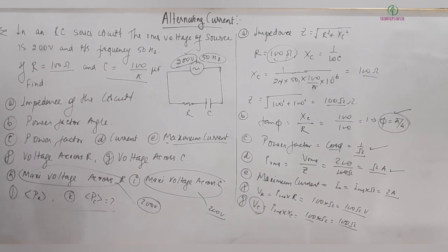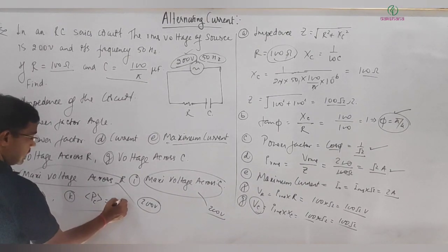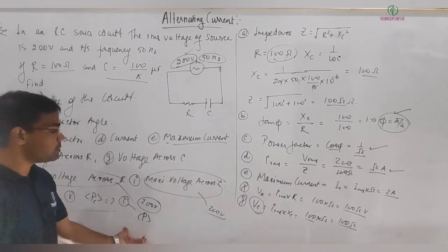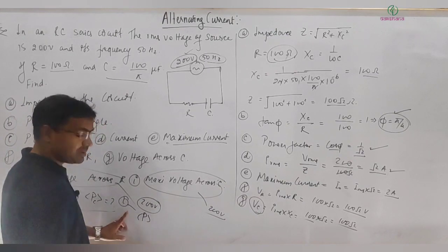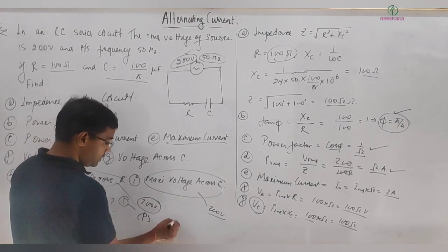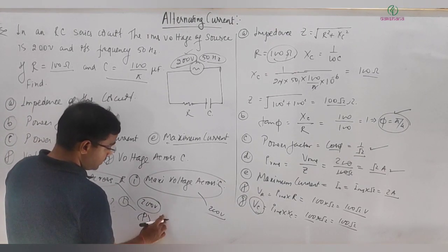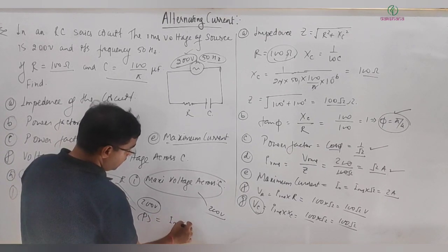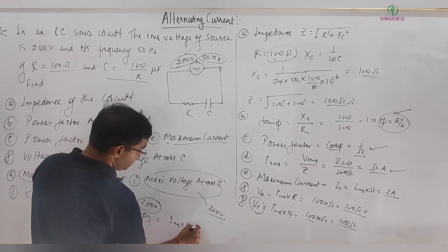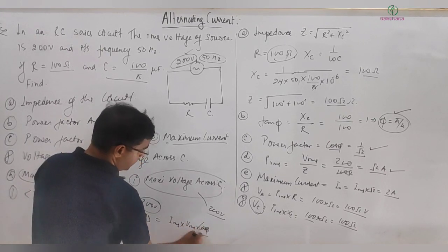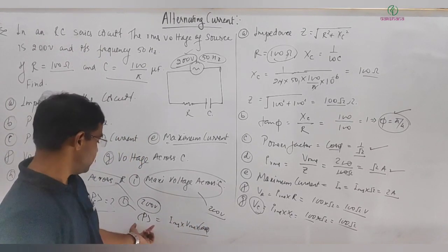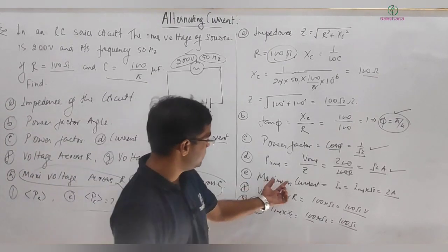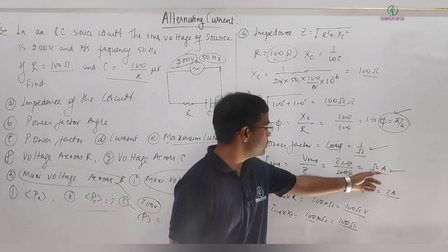Alright, I think there was one more case. So here it's talking about average power. Then average power, what will we write? I'm solving directly for space purposes. So P average, you can write, is equal to what? I RMS into V RMS multiplied by cos phi. Now you have everything. This is for the complete RC circuit. I RMS, we have root 2.